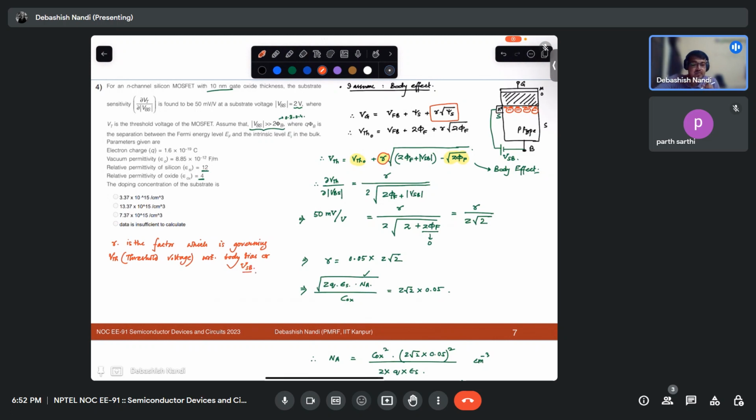Why do we call it body bias? Because generally we take source as a reference potential for 3-terminal or 4-terminal devices. Though body is also taken as reference potential most of the times, source does the same thing. But conventionally or traditionally, source was to be taken.